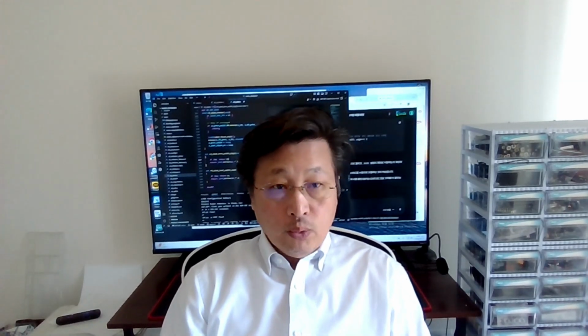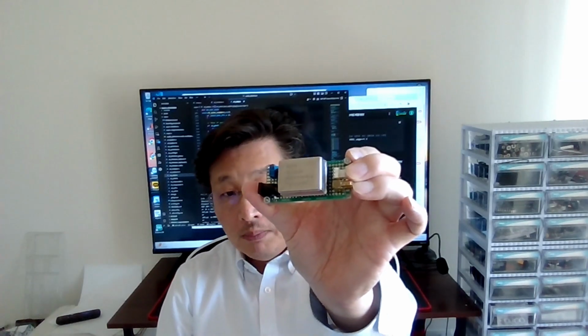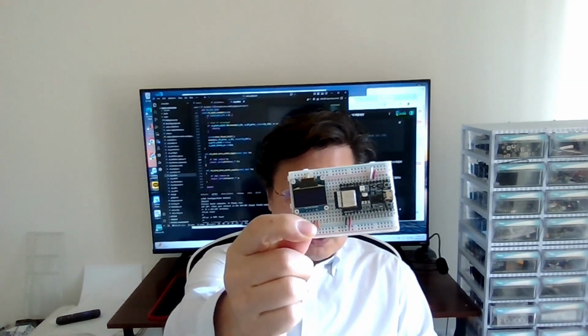Another surprising point is the oscillator quality. When I checked several ESP32 products, I found that their oscillators are usually only around 1 ppm to 10 ppm in accuracy. But in the wireless ranging field, many people believe that if you want sub-meter or even centimeter level accuracy, you usually need much better oscillators, often in the ppb level class. So it was quite surprising that these low-cost ESP32 boards could still produce this level of ranging performance.